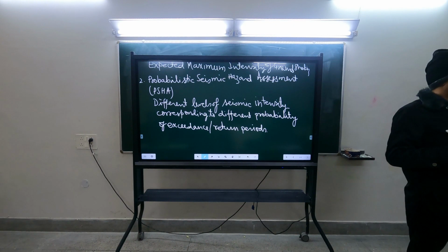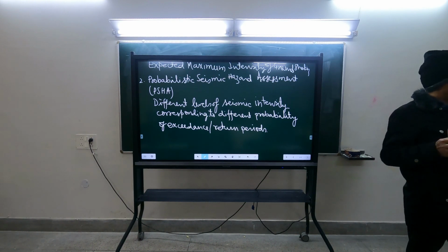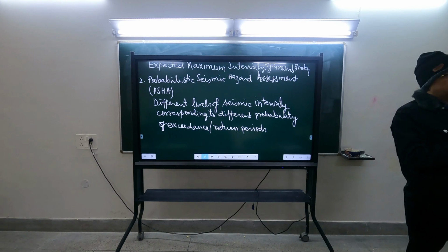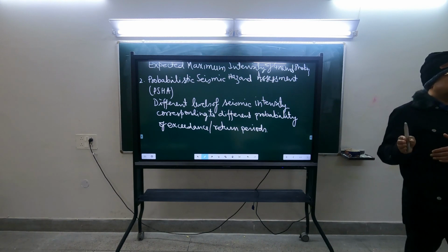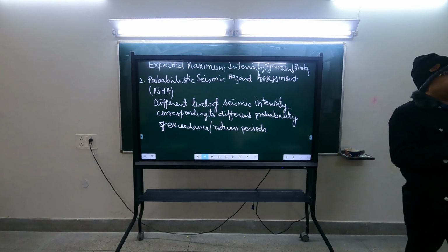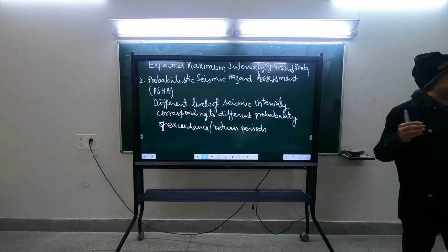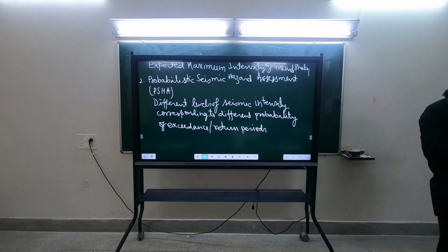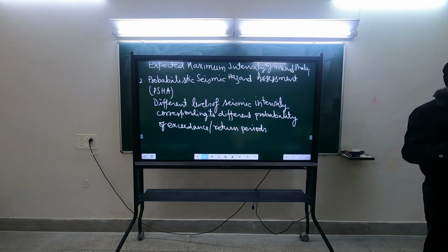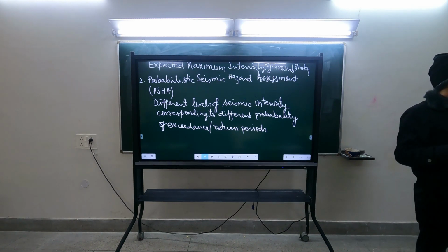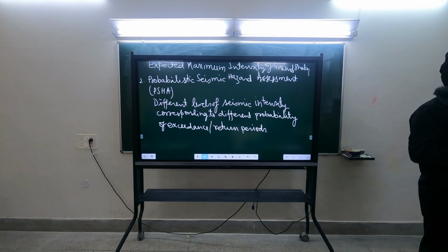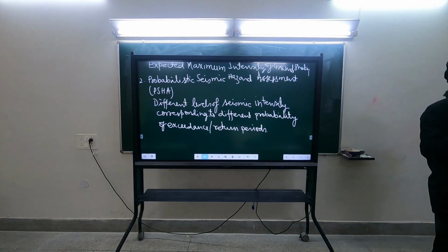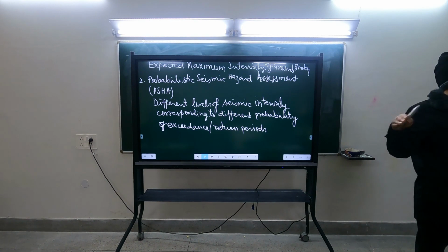But this job of seismic hazard assessment is done by a seismologist. In our department there are three branches: engineering seismology, geotechnical engineering, and structural engineering. Structures will be designed by geotechnical engineers and structural engineers. But what design hazard will be used, PSHA and DSHA, will be determined by seismologists. The job of the seismologist in design of structures is to provide the design seismic hazard corresponding to any return period or a deterministic value. Deterministic value is sort of a theoretical maximum, what you are expecting as the maximum seismic hazard there.